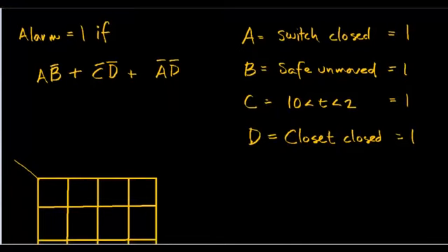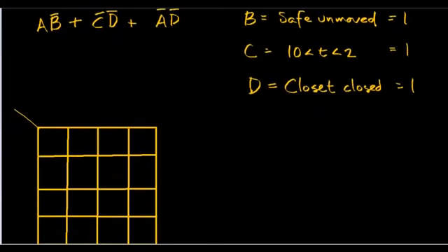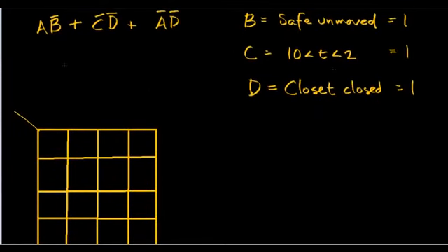And now we're going to take the question one step further, and we're going to try and design a circuit that will actually solve this problem. So let's plug this into a K-map. 0, 0, 0, 1, 1, 1, 1, 0. Okay, let's look at A, not B first. That would be 1, 0. When we have a 1 and a 0, it doesn't matter what C and D are. They could be anything. So all of these would get a 1.